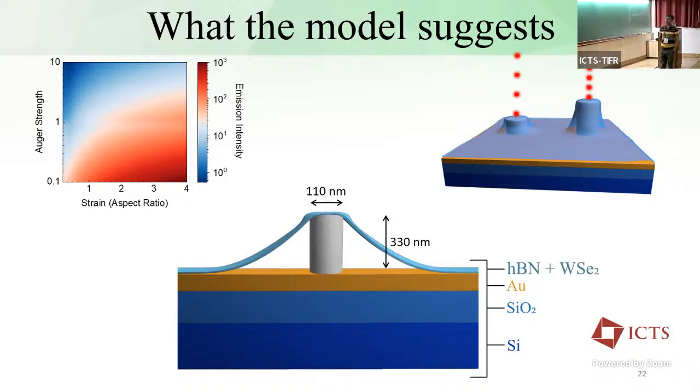And so what we do is that instead of that, we use a photoresist, and this is a negative photoresist, and we bake it, and that gives it enough mechanical strength, and at the same time it's so-called soft enough that it doesn't punch through. So our yield was pretty good. I'll show you some data after this. So this is sort of working well.